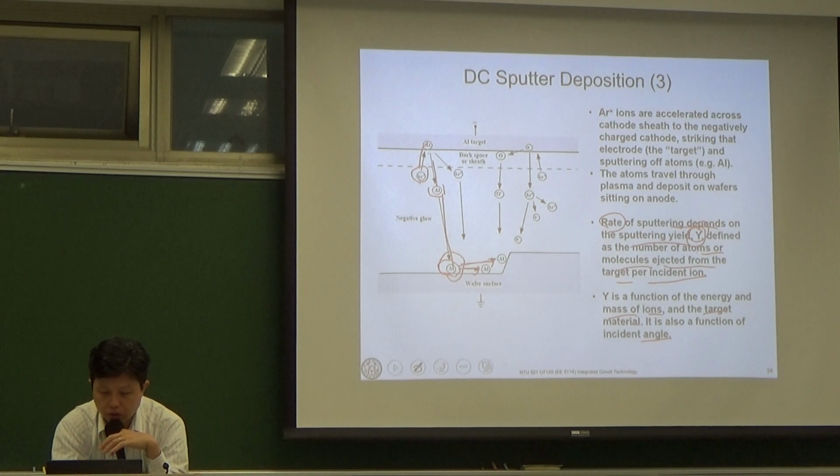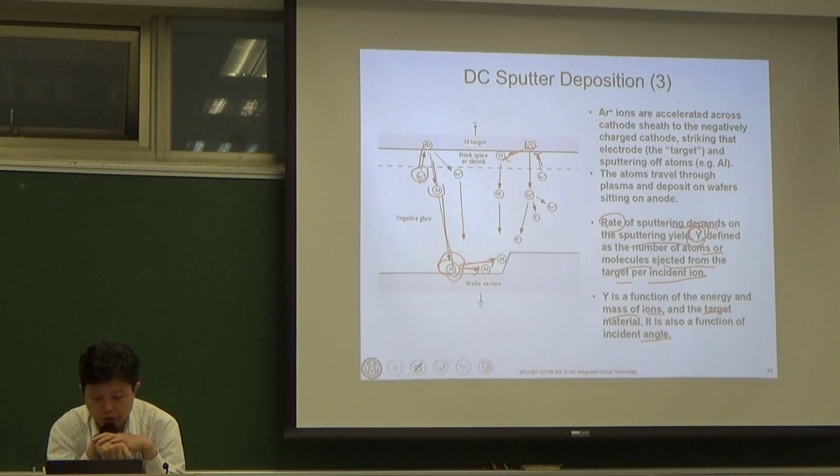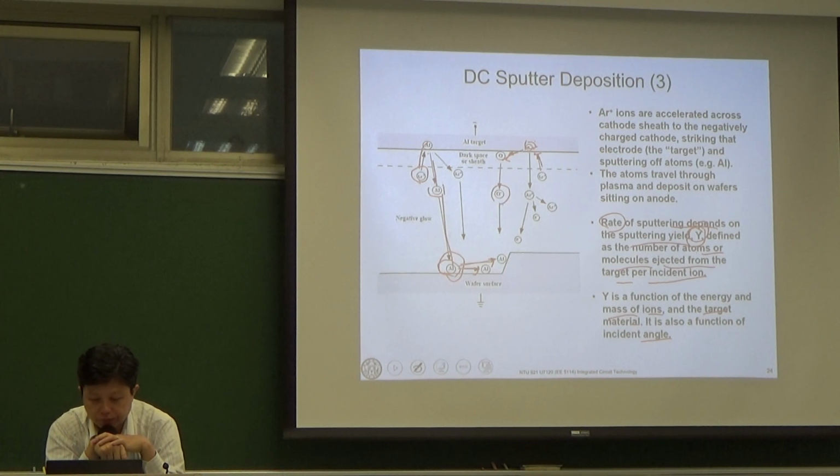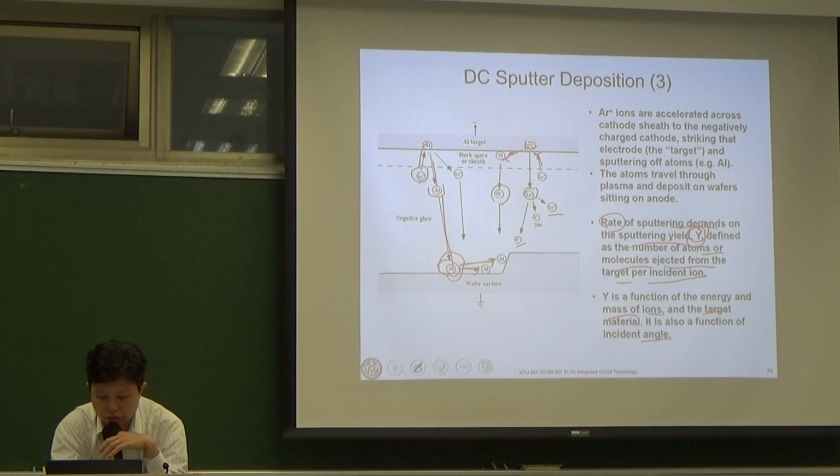And also, you have argon sputtering here, and you have some electrons coming out, because this chamber is not at very low pressure, so you still have some oxygen here. They will move. You have some oxygen ions here, and you have this argon radical. They can continue to give out the energy and become these electrons and also the argon ion.